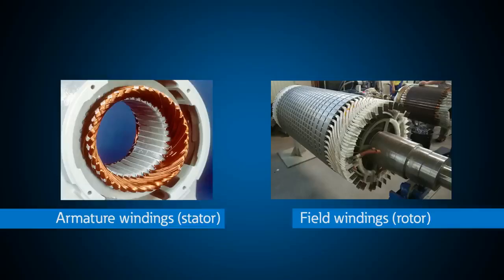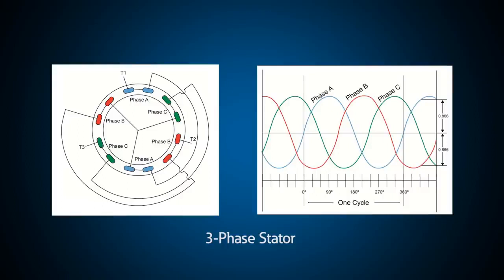The stator windings tend to be larger, highly insulated, and more complex than the field windings in the rotor because they must carry the generated power through them that is of a much higher voltage. A three-phase stator will consist of 3 windings, where for each phase there is 1 group for each rotor pole. Each group is interconnected and can be considered as one large coil. Each group has an output lead from a generator that is 120 degrees from one another. The leads are typically Y or star connected, and the neutral is usually connected to ground or brought out with single-phase loads. As the rotor spins, 3 separate voltages are created at the stator terminals.